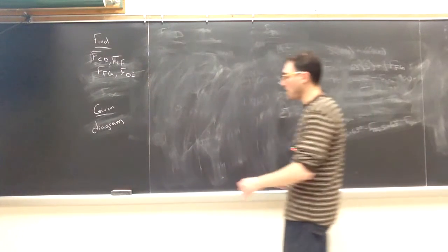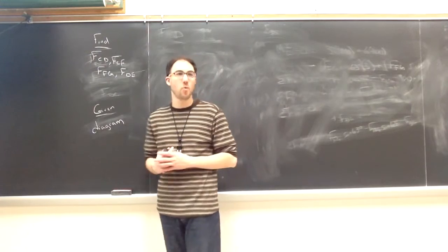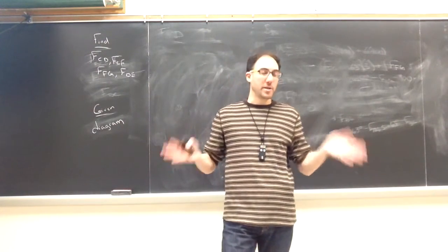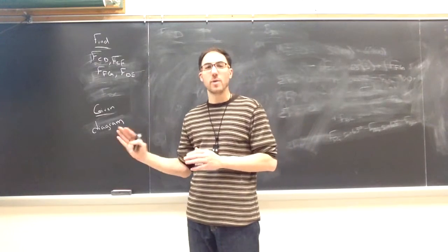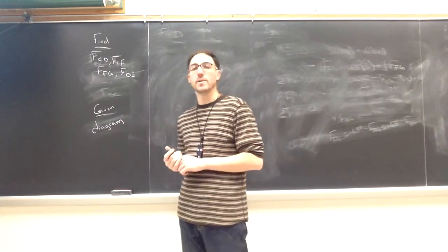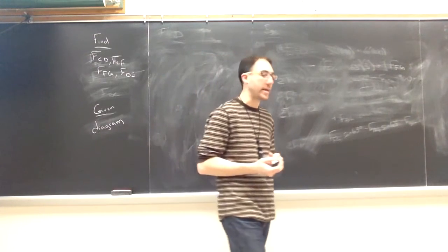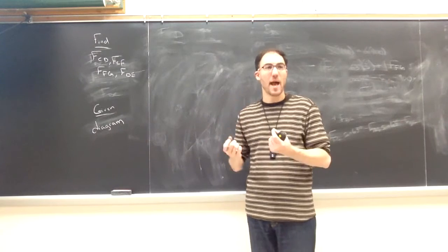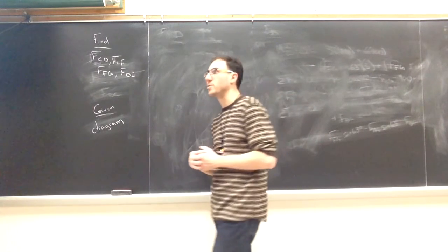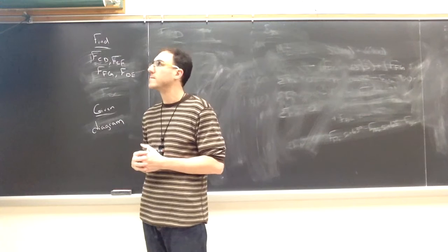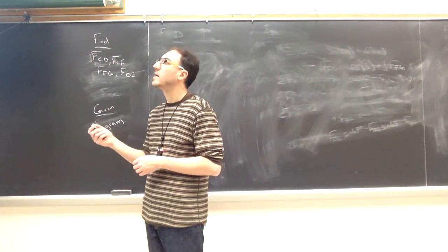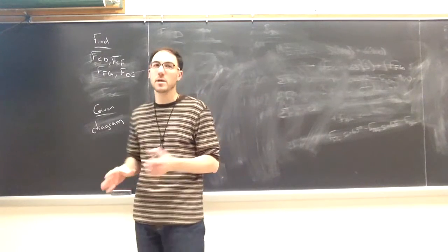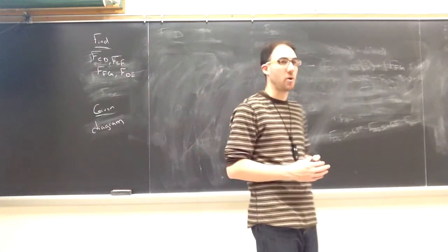With this in mind, that we're only interested in the forces in these 4 members, what would be a good, well, actually taking a step back, we first want to analyze our entire system, and we want to see is it statically determinate or statically indeterminate. Looking at how it's supported by the ground, we have a rocker at E, and we have a pin at A. So we have 3 reaction forces, meaning that this is statically determinate.